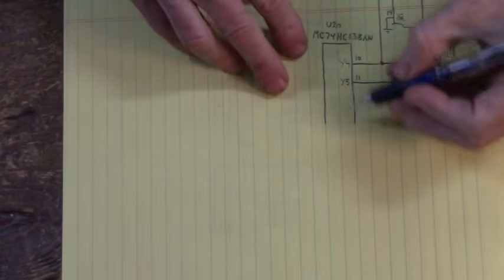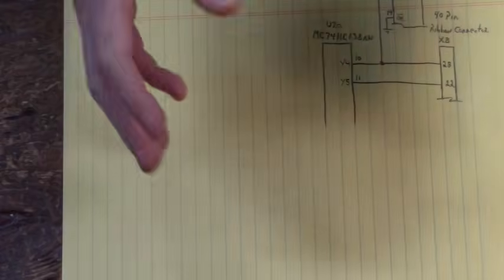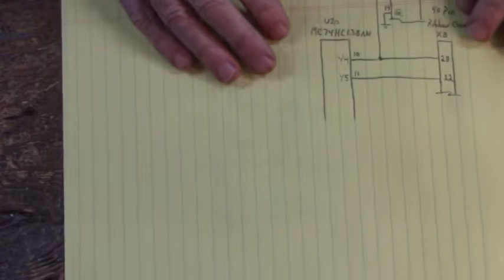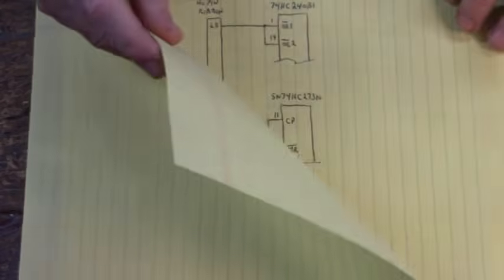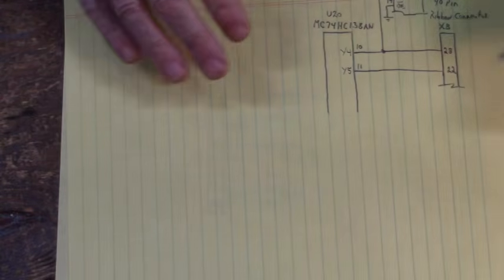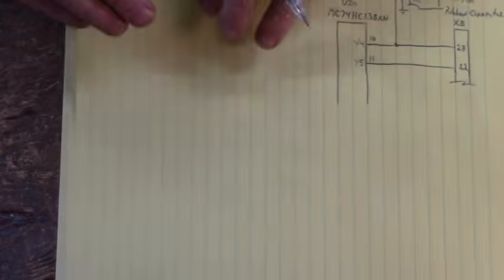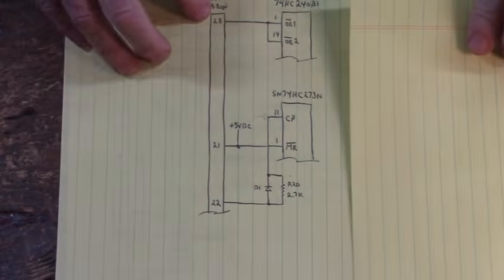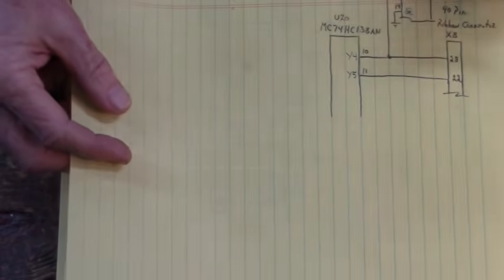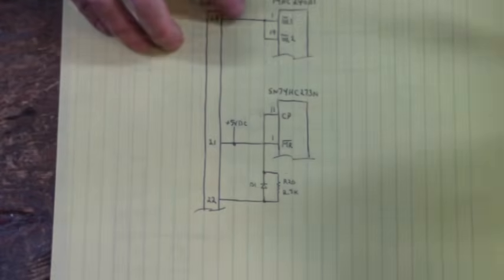And you'll see these ICs a lot for addressing, and that's what we're basically doing. We're addressing those ICs. This is on the control board. So 22 and 28. Here's 28, here's 22. That's your clock and your output enables.